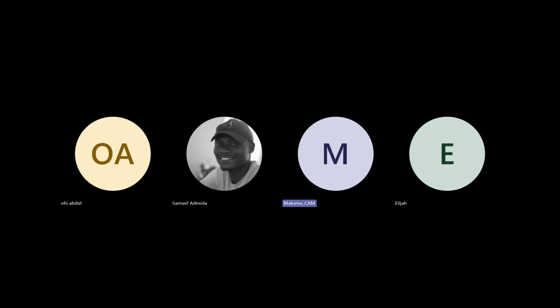If a motor is spinning very fast, you can put a very small gear on its head to spin a very large gear. Before that large gear spins 360 degrees, the small gear needs to spin maybe over 30 times before it makes the big gear spin one time. So you have reduced the speed of the motor while increasing the torque. You see how important these gears are.